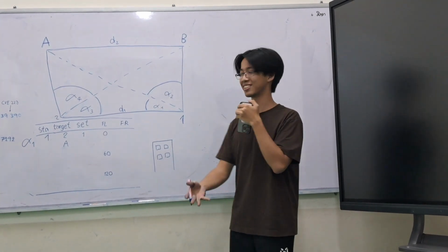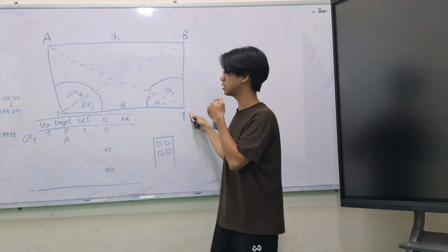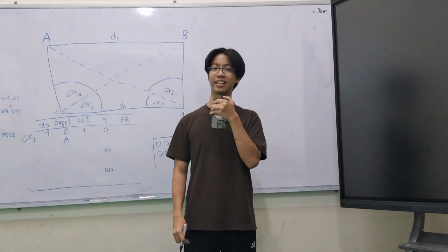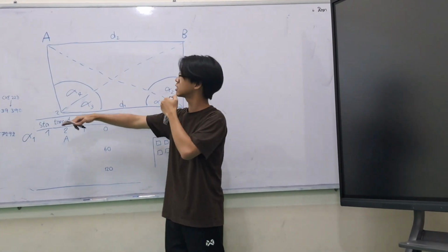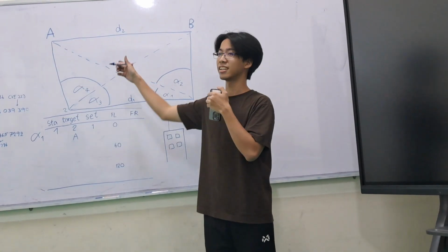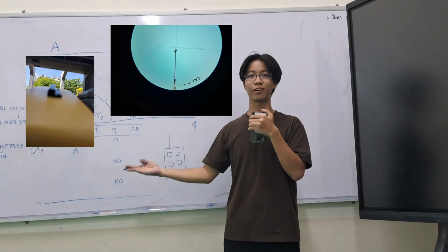First, you need to put your total station at point 1 and your prism at point 2. Point your total station at the prism, set the angle to 0 degree, and then turn your total station to building A. For point A, the point that you need to measure is the tip of the steel rod of the building, as in the picture that I already inserted here.